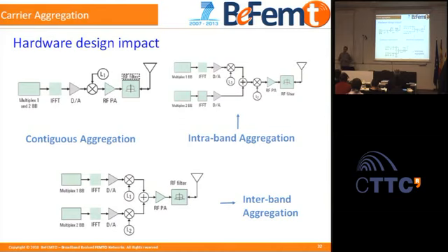But if the power amplifier is such a wide band, there are going to be intermodulation products. Yes. And if you have a wide band filter as well, how will it filter out those intermodulation products? The filtering can be handled here, for example. If you filter one band here and the other band there, in principle there's no problem.